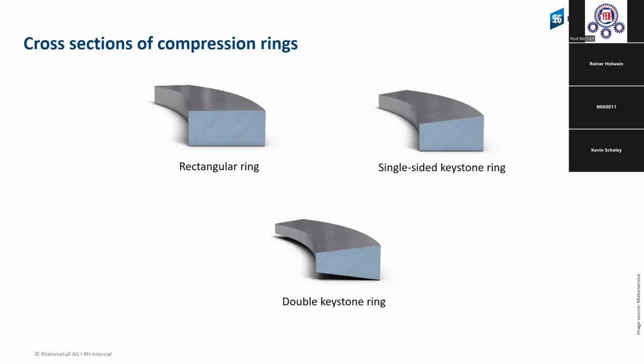The biggest problem is in the first ring groove, when we have no load on the engine. As I said before, we have no pressure behind the piston rings. Then the pressure from the piston ring to the cylinder surface will be less, and it cannot seal and cannot scrape the rest of the oil down. That means oil comes to the combustion area and burns, and then we build up carbon. When oil is burned, it's too hot, and then carbon builds up.